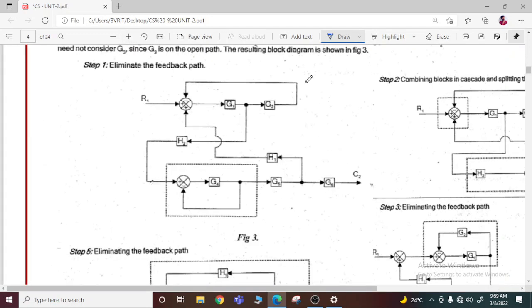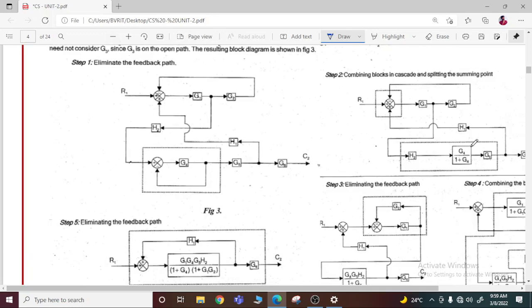I have eliminated this C1 part as well as the R1 part. So this is my R2 part, and this is my diagram now. Again same, eliminating the negative feedback. So here this is my resultant one after eliminating the negative feedback, and after that if you come from here, again what are the blocks which are connected in cascade? H2, this negative feedback, G5 and H1, right?